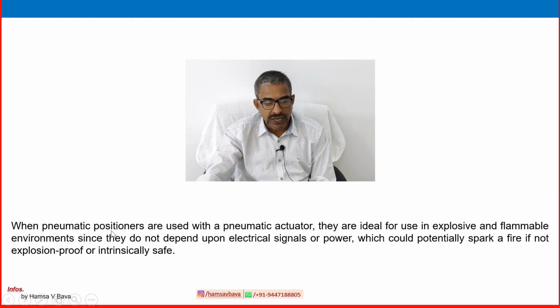When pneumatic positioners are used with pneumatic actuators, and I told you that positioners we have to study separately, they are ideal for use in explosive and flammable environments, since they do not depend upon electrical signal or power, which could potentially spark a fire if not explosion proof or intrinsically safe. So that is also another advantage.